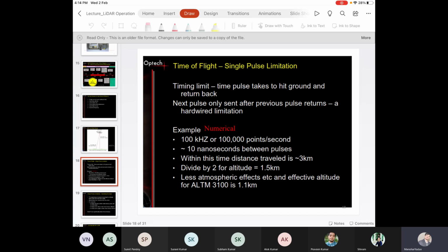If you are firing multiple pulses at a time, the internal receiver unit can't identify which fired laser beam the returning signal is from. So that was the reason why that sensor's receiver transmitter doesn't fire the next pulse till the receiver received the return of the first pulse.